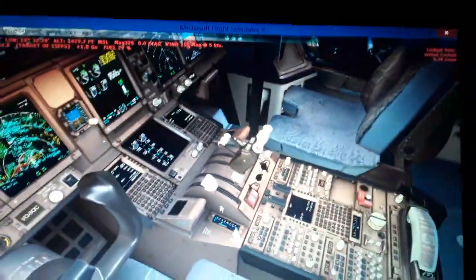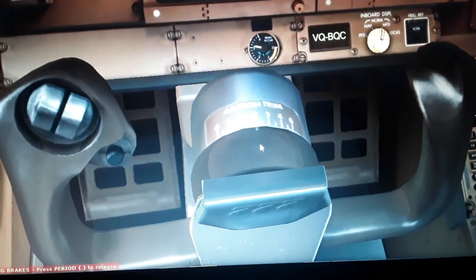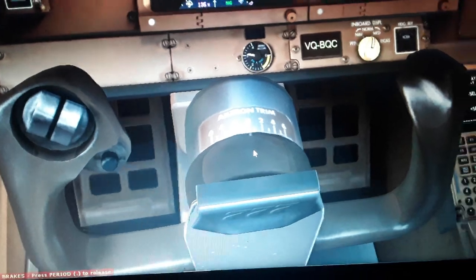Maybe we can make now the rest of the systems, like the thrust levers. You will see here we have the autopilot disconnect, the aileron trim, the control column and yoke. So this is the horizontal trim of the horizontal tail stabilizer, the rudder pedals. So we have the position here of the horizontal tail trim stabilizer, up and down. You can see the green band is mainly for takeoff. So the normal alternate control pads.